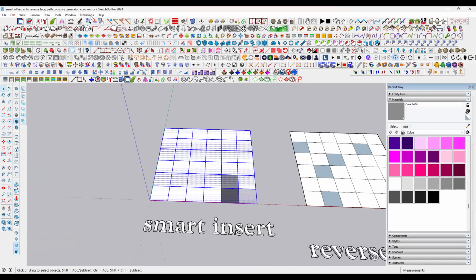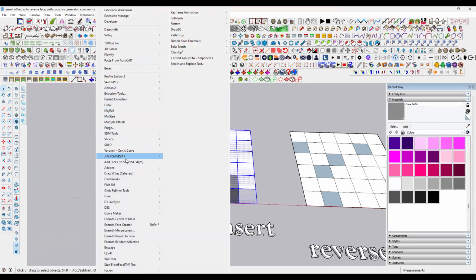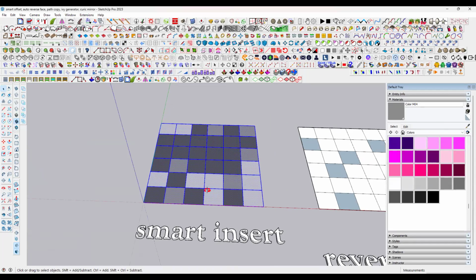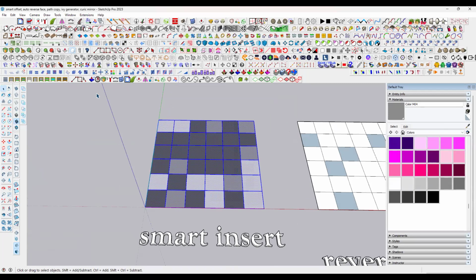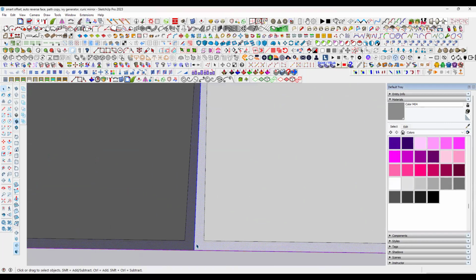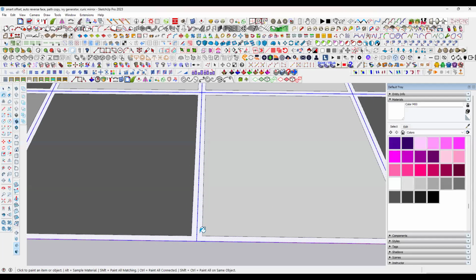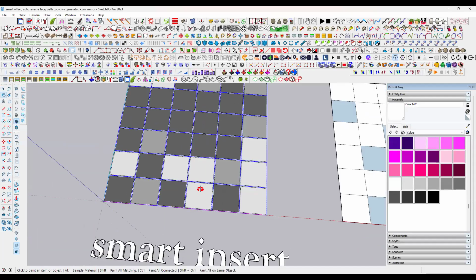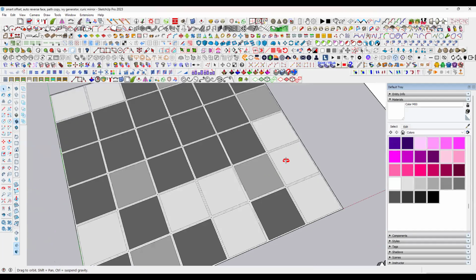Then I'm selecting everything, then going to Extensions, and here I'm going to apply some Crease Full Mark tools and Extrapolate Colors. Apply that. Then select everything. Then I go to this plugin, Smart Insert Tool, and I'm giving minus 0.2 inches. After applying this 0.2 inches, wherever you have this gap, I'm going to apply the white color. See, automatically it now looks like a tile design.